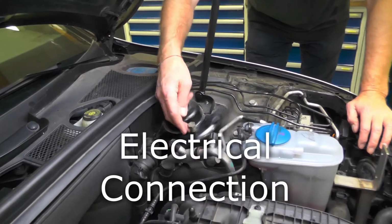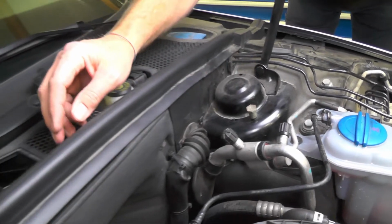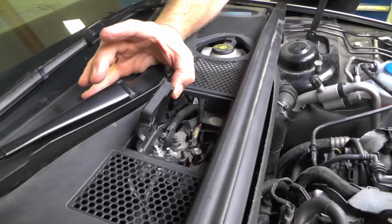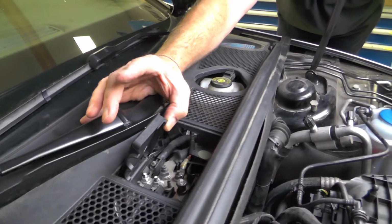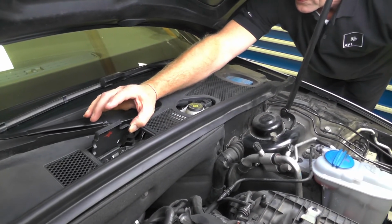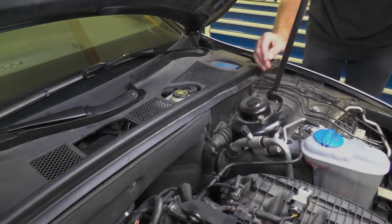For electrical connection we need to connect to the mass or minus pole, of course, and to the plus supply of the vehicle, which connects to the battery in the trunk. So for the supply connection of the PLUtron flow meter we will connect here and here.